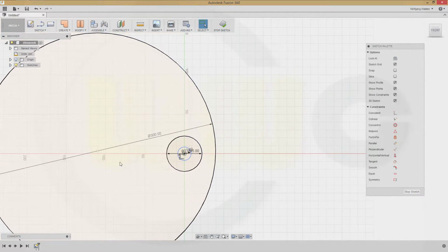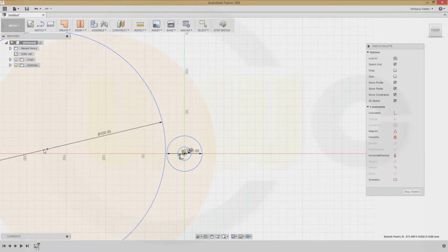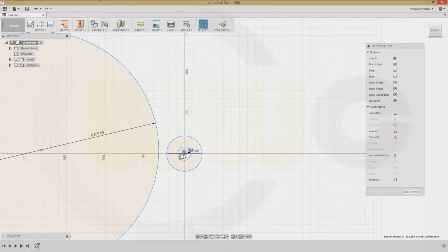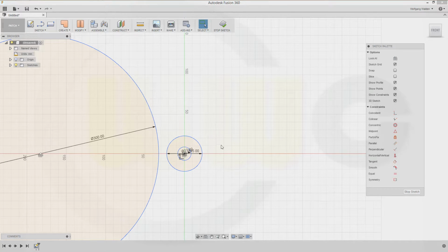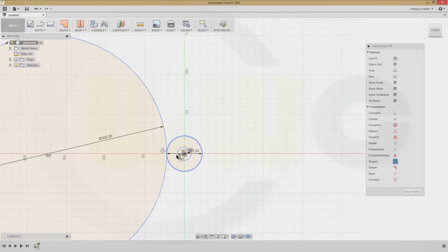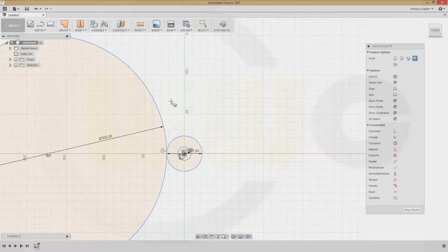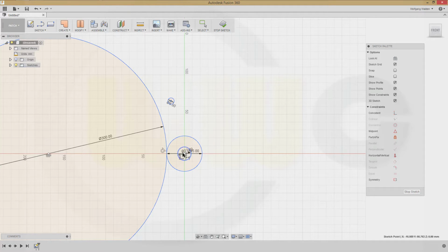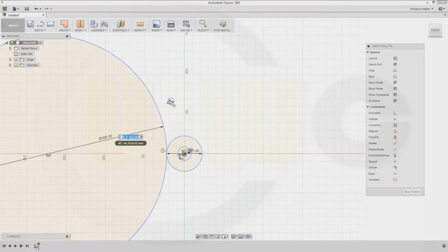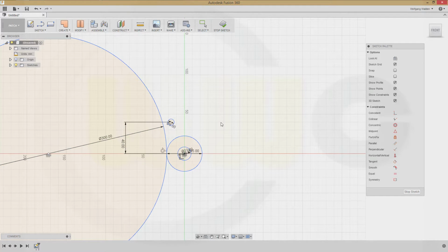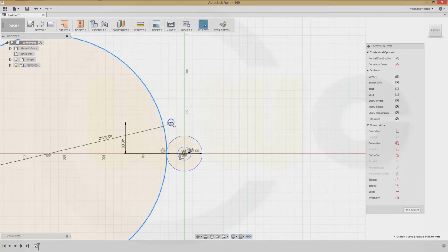and move this over here and make these 2 points aligned horizontal, and these 2 should be tangent. I need another circle. Diameter is 8. There should be a dimension from this point to that point, which should be 40. Now make these 2 circles tangent.